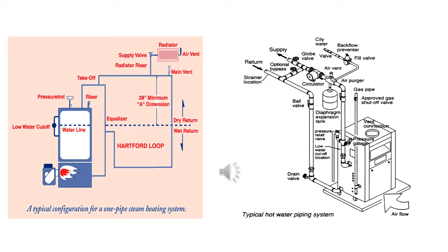Boilers also have a means of protecting the boiler from excessive pressures and from the water level in the boiler becoming too low. A forced hot water boiler is designed to heat the water, and the heat energy from the water is transferred to the conditioned space. Since there is no change of state and only a change in temperature, the type of heat energy used is sensible heat. So for every pound of water in the system dropping 1 degree Fahrenheit, it will deliver 1 BTU.